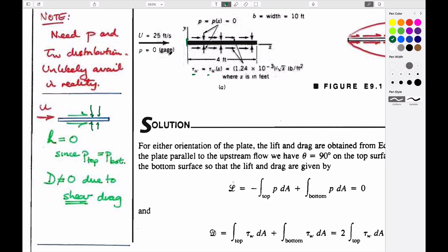No shear stress in this, because the shear stress would have to be acting on this. And actually, if you think about the shear stresses, if you blew up a portion of this and made it much larger, so if you made it thicker like this, the flow is coming in here and splitting below and above, the shear stresses resulting from this would also directly cancel out. And they'd be trivial because it's such a small area. So in other words, it's a finite shear stress, but it's a tiny area, so they'd be small, but also by virtue of the fact that it's symmetric, they'd cancel out as you do the integrations.